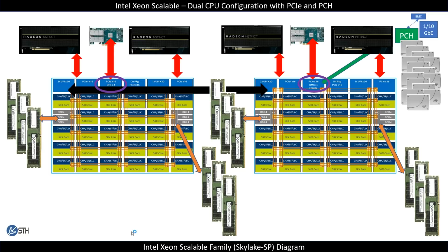While we like the AMD EPYC flexibility, Intel's platform really doesn't stop at PCIe lanes. It goes a little bit further. So what you'll see is a DMI by 4, so that's a PCIe 3 x4 link to the PCH hub. And in this generation, the PCH can have up to 14 SATA devices. So we have SATA SSDs here. Realistically, due to bandwidth constraints, you probably want to have only a few SATA drives, or you want to have SATA hard drives, but you still get those for only 4 PCIe lanes.